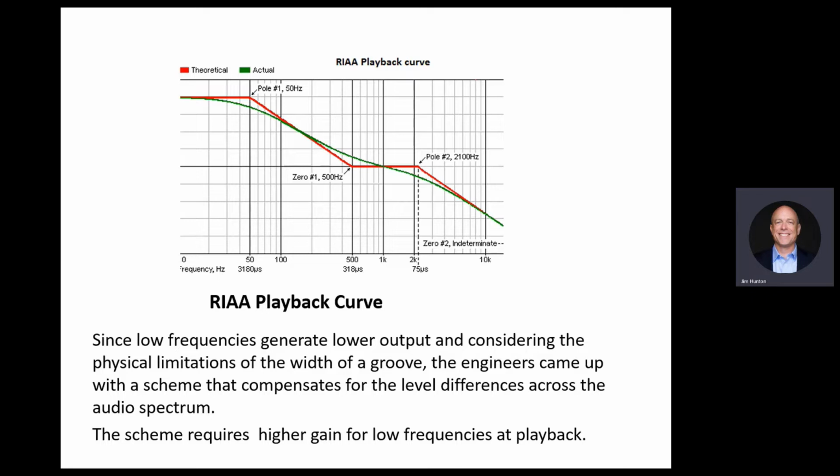We put a low pass at the first frequency, first order. We put a high pass at this frequency, also first order, so the slope becomes straight. Then we put another low pass here. All of them are first order, essentially. Very simplistic circuits.